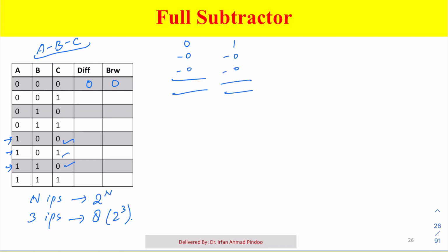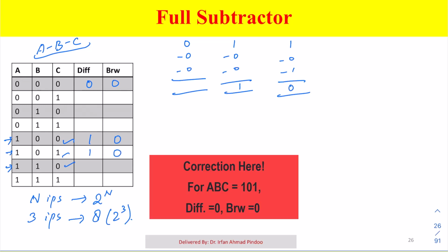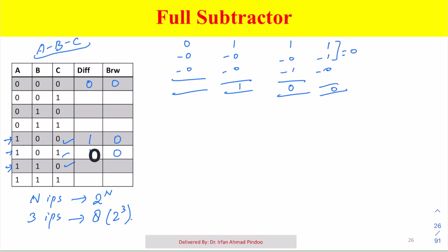The difference will be 1, and there is no need of borrow here, so this is 1 with 0. Similarly, what is 1 minus 0 minus 1? 1 minus 0 is 1, 1 minus 1 is 0, so again there is no need of borrow. The last easy one is 1 minus 1 minus 0. 1 minus 1 is 0, 0 minus 0 is 0, so this is 0 along with borrow, again 0.